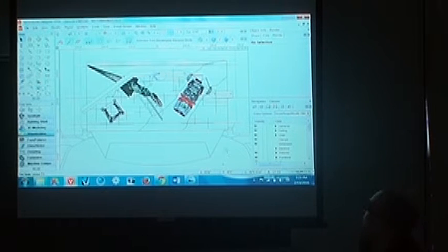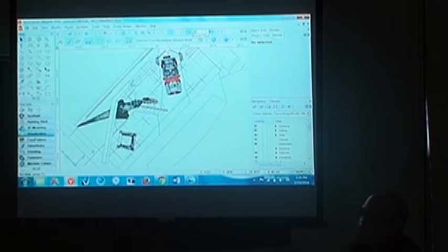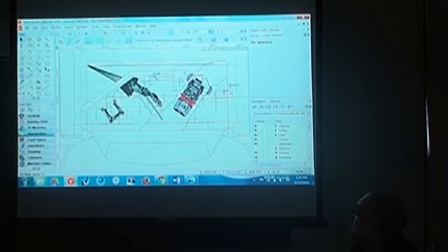Using plan rotation, this is something that I haven't even really used much, and I kind of completely forgot that you can even do it. But if you create objects and you end up rotating them into, not being perpendicular to the XY plane anymore, you can actually just rotate your entire drawing plane and then work at that angle to do whatever you need to do, and then put it back. If I just select top plane again, it should go back to straight.